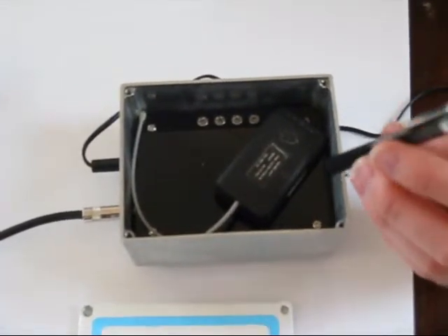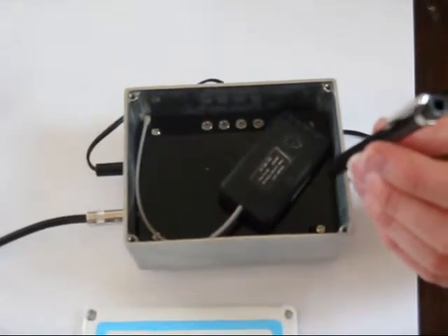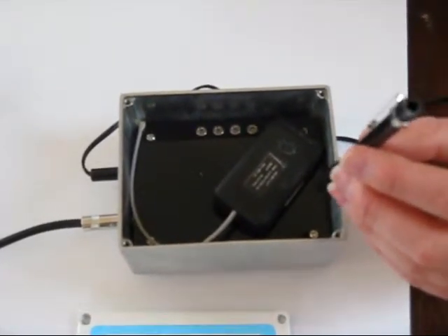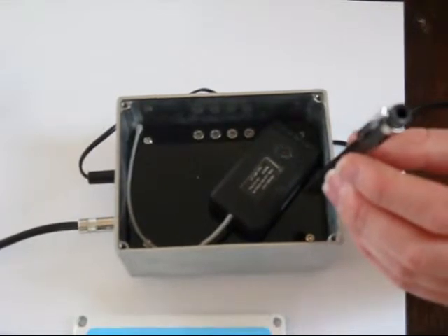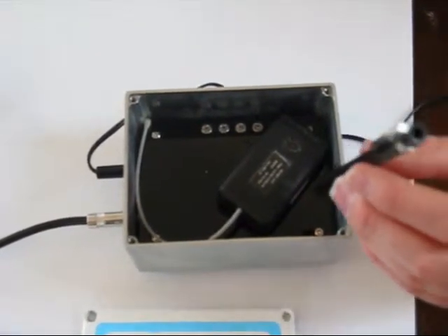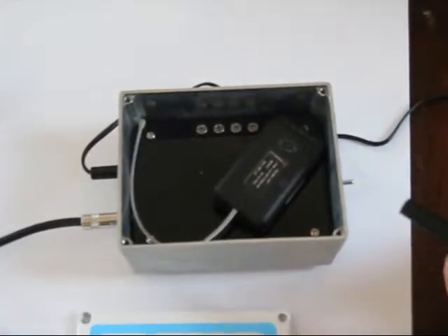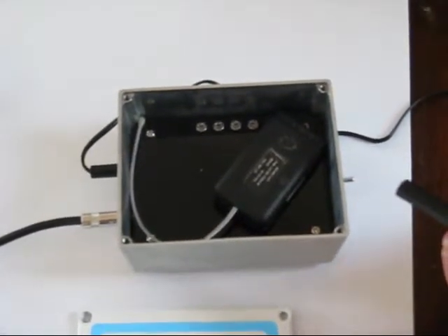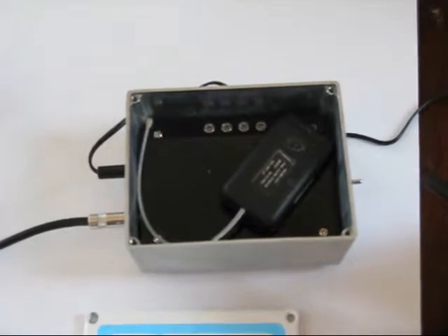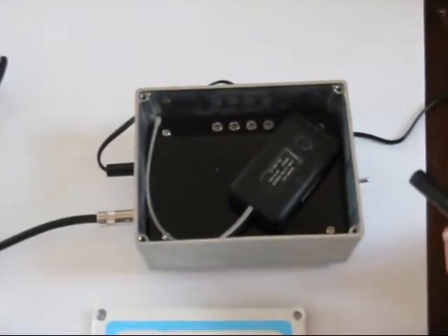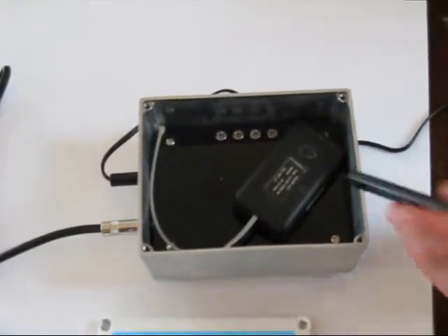You'll then need to take the magnet pen away in the 1 to 2 seconds after the bug finder has stopped continuously beeping. After you have taken the magnet pen away, you'll need to listen for up to 5 seconds before the background pulse rate will start. The transmitter is then turned on. I'm now going to demonstrate doing this.